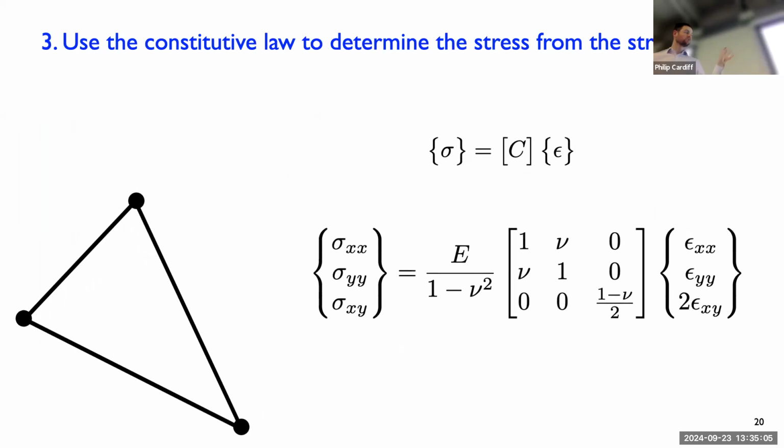So in 2D, assuming linear elasticity, it will look like this. There's lots of ways we can write this stress equals strain in 3D. We can write it in Einstein or index notation or in tensor notation. But for our finite element approach here, this is the most convenient. So what does this say? It says, let's say XX stress is equal to row by column. Let's first imagine the Poisson's ratio is 0, because this has a direct analogy with 1D, which we've already done. So let's imagine this mu here is 0.